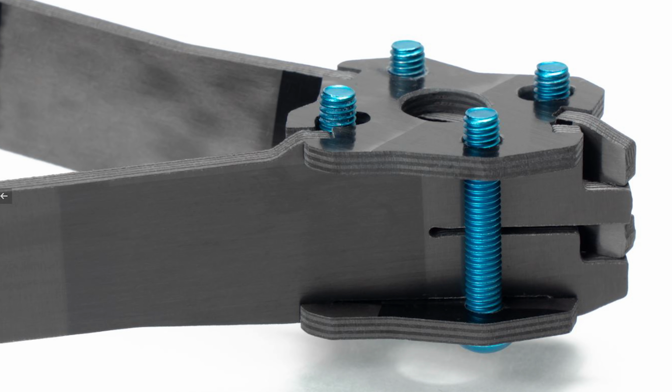Yeah, I think we have a feed rate of, it's crazy, like 2.8 meters per minute or something like that. Wow. Yeah, I mean, compared to the 1 millimeter radius that I usually use. The 1 millimeter radius, they're using 0.15. Yeah, exactly. And it's less than a third of that. So we can cut way faster than you can. And then, of course, all the way through in one go. So it's really fast when you're cutting.